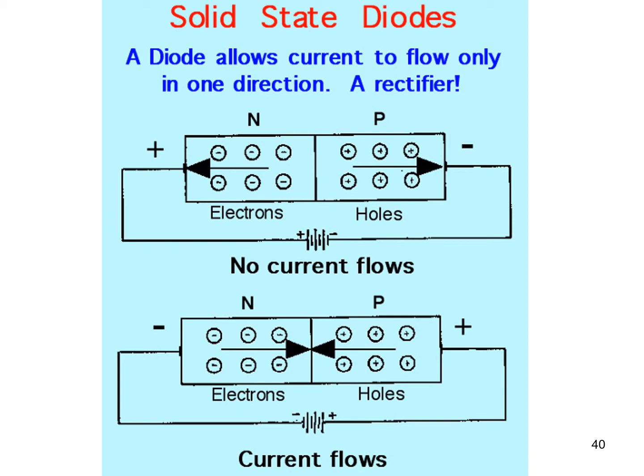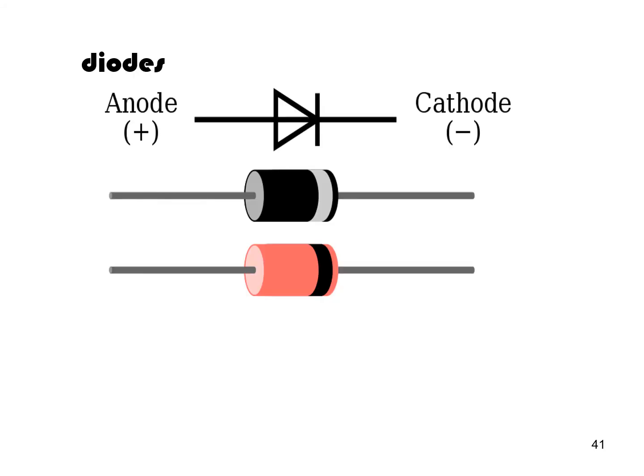That's the point. If we had a pure silicon crystal, or even silicon doped with the phosphorus or the boron alone, we'd just have built an expensive conductor. The key to these is to marry an N-type with a P-type. That's why you cut them into those thin wafers, so you can put them together and get a P-type and an N-type. And this leads to our first device made of semiconductor materials, and these are called diodes.